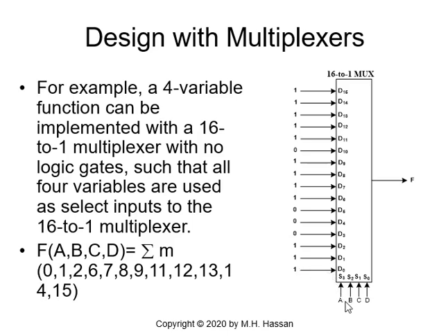Now, when we have 0, 0, 0, 1, I'm selecting D1. Do I have 0, 0, 0, 1? I do have the minterm 1, which is S3 prime, S2 prime, S1 prime, S0. Since it is there, it is M1 and D1 has to be 1. So M1 D1, D1 will be 1.